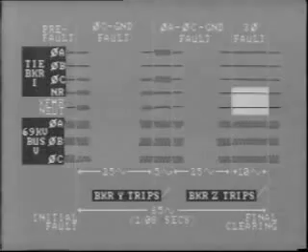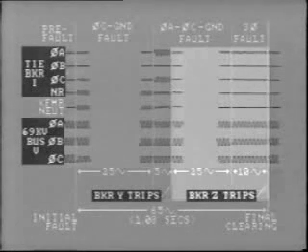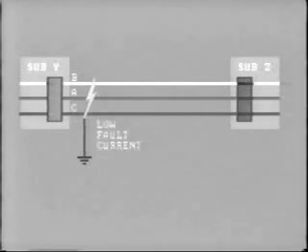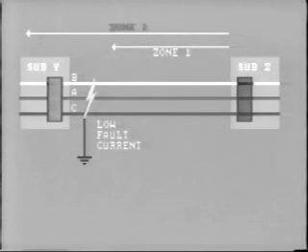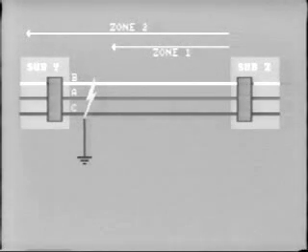You can see this from the 3 fault currents in the tiebreaker and the fact that neutral and residual currents are now 0. Breaker Z at the other end of the faulted line now trips to completely clear the fault. This occurs 35 cycles after breaker Y trips. Again, this is reasonable because the fault current is low and also because the fault is in zone 2 of breaker Z's protection. Thus, tripping is further delayed.